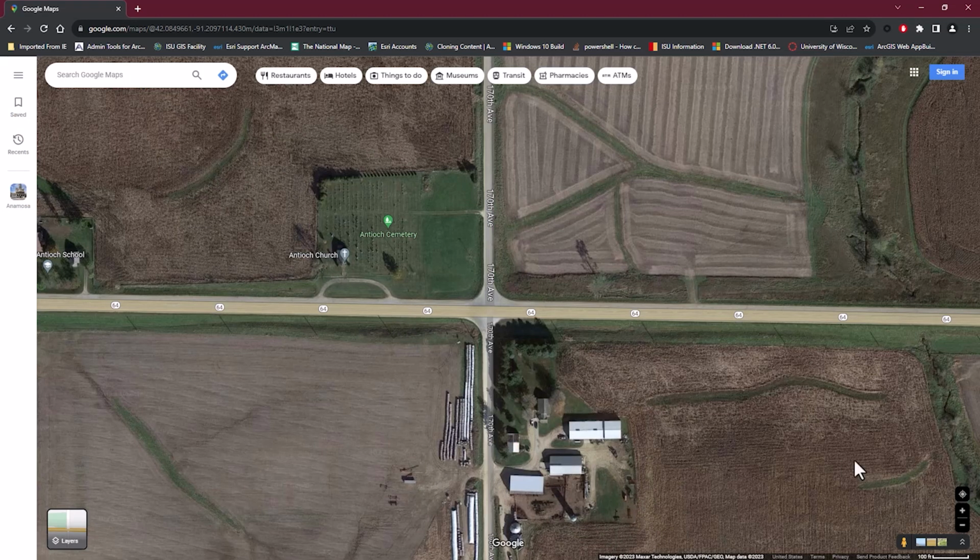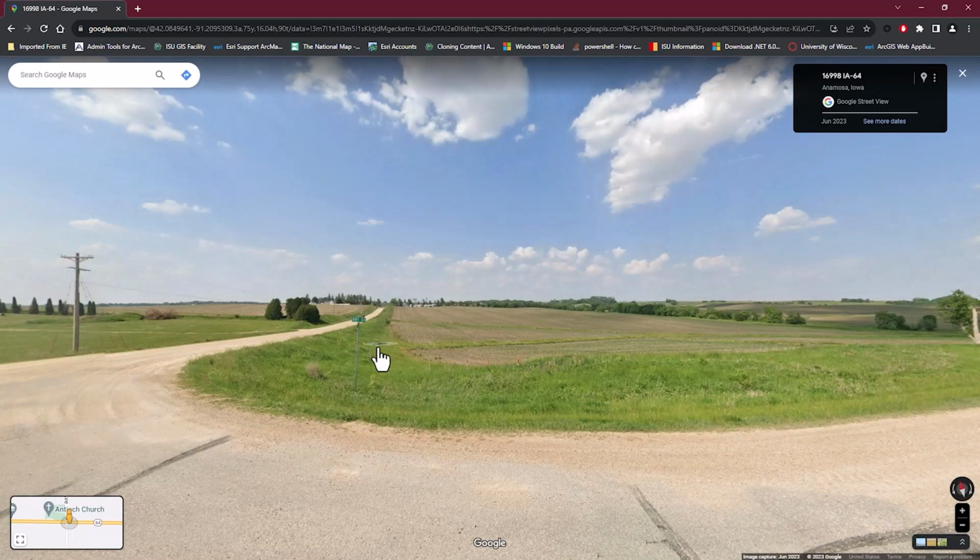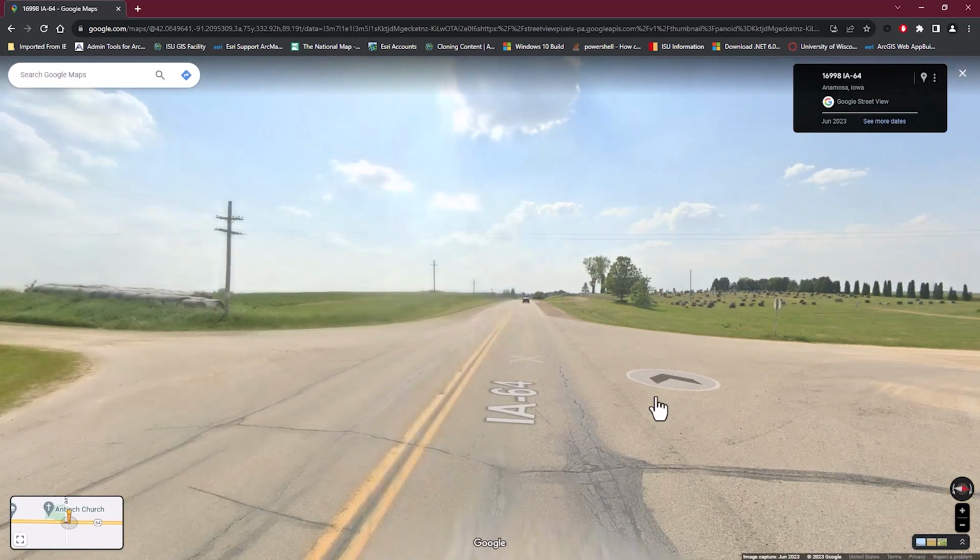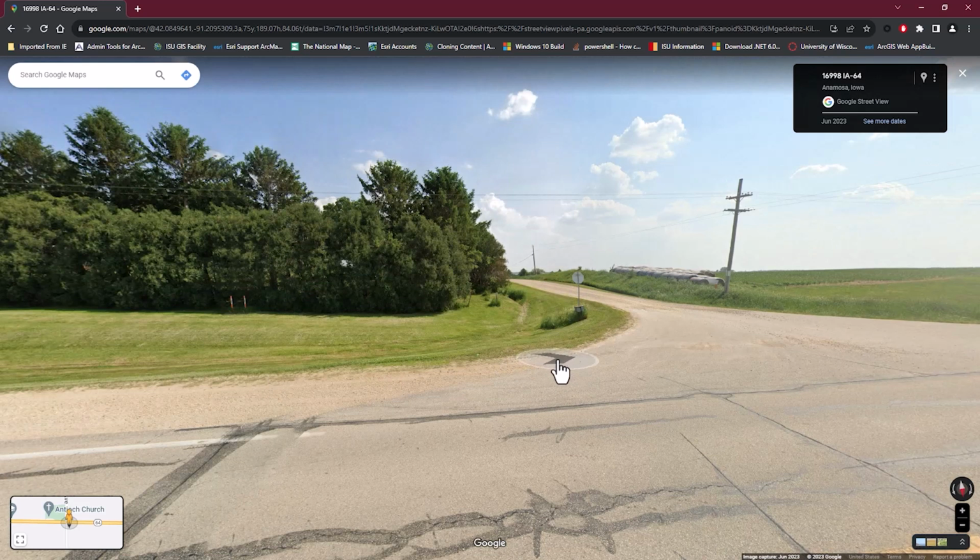We can click and hold on the person in the lower right corner of the window, and we can see that the road turns blue, so we know that there is street view. We can place him at this intersection. If we look towards the south, we can see a small area of tall grass along this county road. This is most likely where the culvert is, as the homeowner cannot get the mower against the culvert. We will place our cut across the county road at this intersection.